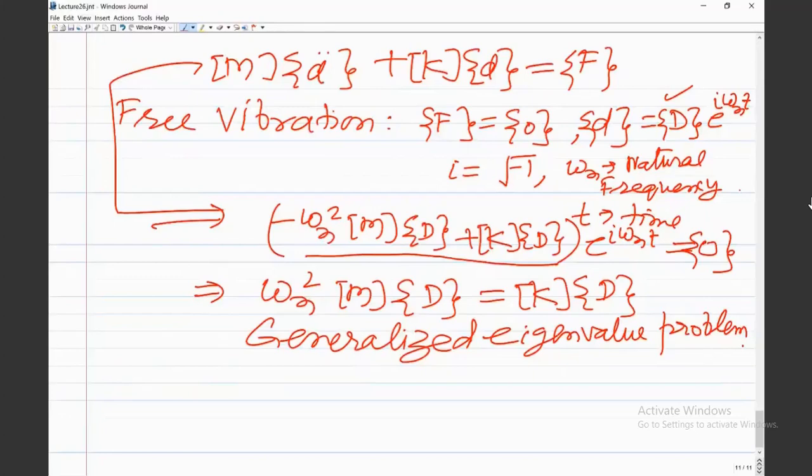One is that if you use the viscoelastic constitutive relation, from there you will get the dissipation terms automatically, because you consider the viscoelasticity. But if you want to consider an elastic model, then the dissipation has to be empirically incorporated in the equations of motion. So that is what I'm going to discuss, how to get the damping matrix.